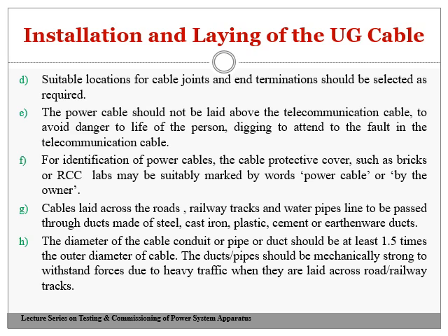For identification of the power cable, protective covers such as bricks or RCC slabs may be suitably marked with the power cable or by the owner. The cable route has to be specified, and the state authority should follow some strict rules.